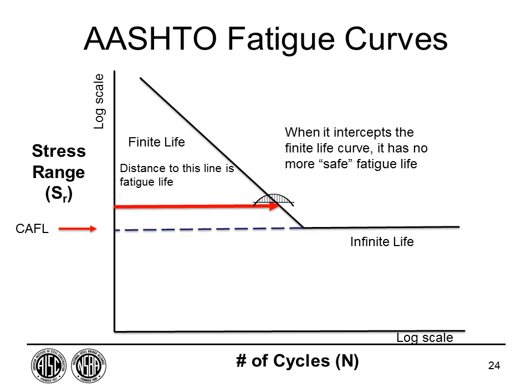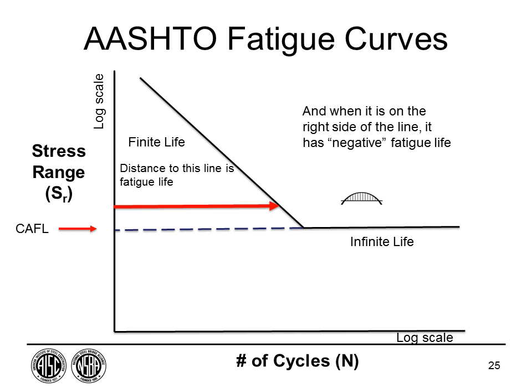But remember, that curve is statistically based, which means there's a 97.5% probability that it would not crack. But that's what we use for design. And of course, in older structures that have been out for a long time with stresses, sometimes we would then actually calculate a negative fatigue life. But again, that's with respect to a safe life. So although it's still standing, it obviously truly isn't negative. It just simply means that we're using up some of the safety margin, if you will, on the structure.